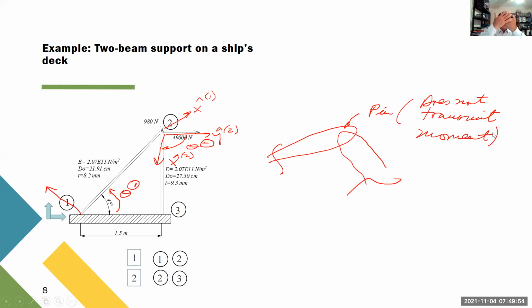See, you have two things like this, and you put a pin like this, okay? The two elements can rotate freely, one with respect to the other. Yeah, but there is no pin, so that is the question. Exactly. In this case, there is no pin, so that's the same corner, like this. So this end cannot rotate freely with respect to this one.